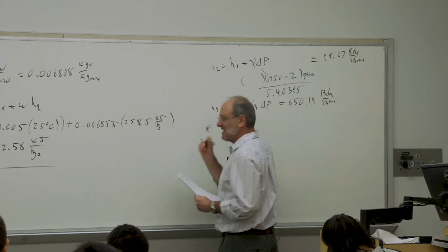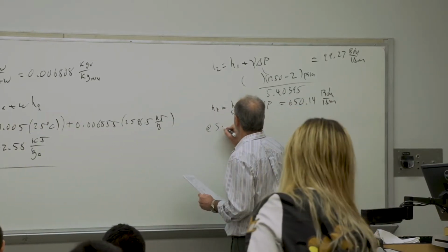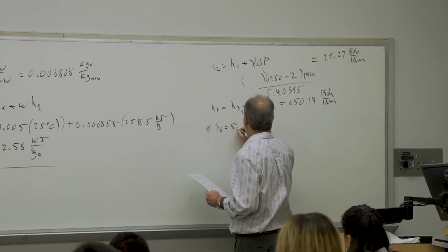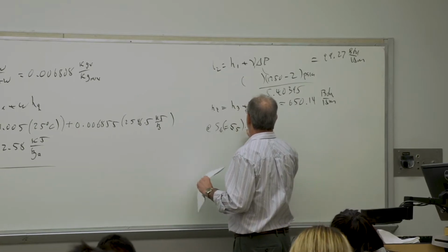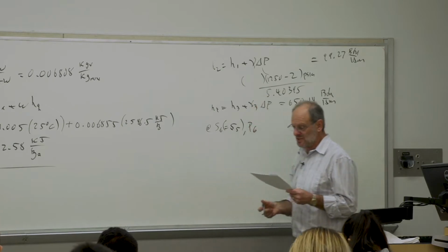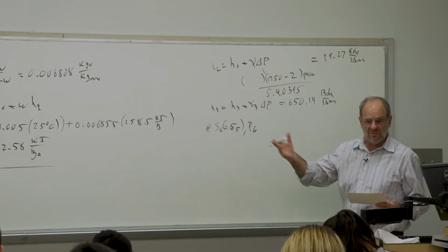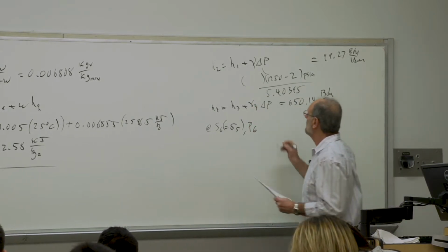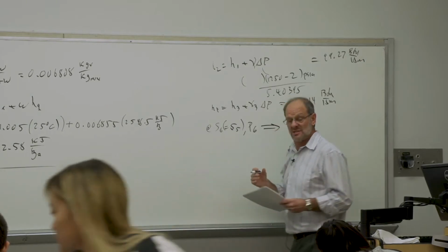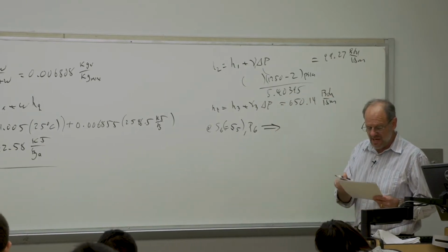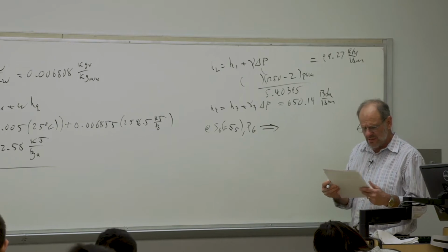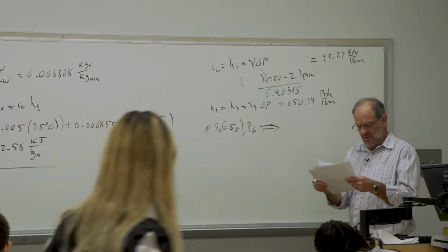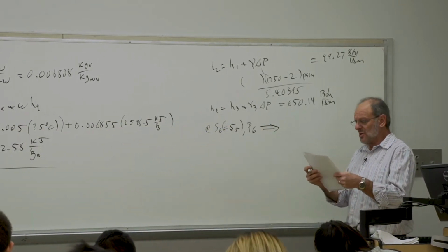So we recognize that it's an isentropic process, so at S6, which equals S5, and at the pressure at 6, which is the intermediate pressure of that feed water heater, 1750, it is superheated.